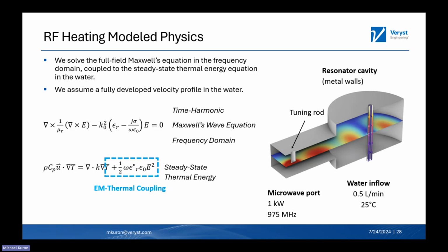Now, in general, the loss tangent can be quite sensitive to the temperature itself, so these are often temperature dependent. If you ever tried to microwave water, it's a very good receptor of RF energy or microwave energy up until the point where it boils, after which it is a very poor receptor of microwave energy.